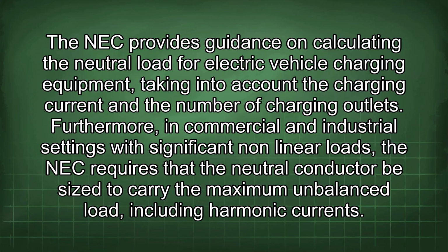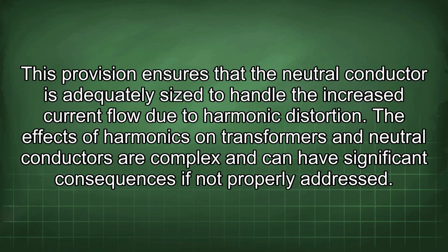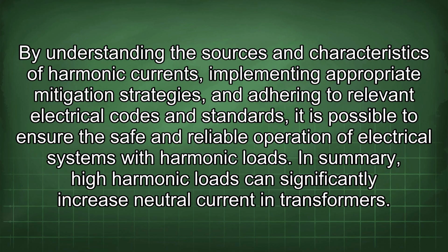Furthermore, in commercial and industrial settings with significant nonlinear loads, the NEC requires that the neutral conductor be sized to carry the maximum unbalanced load, including harmonic currents. This provision ensures that the neutral conductor is adequately sized to handle the increased current flow due to harmonic distortion. The effects of harmonics on transformers and neutral conductors are complex and can have significant consequences if not properly addressed. By understanding the sources and characteristics of harmonic currents, implementing appropriate mitigation strategies, and adhering to relevant electrical codes and standards, it is possible to ensure the safe and reliable operation of electrical systems with harmonic loads.